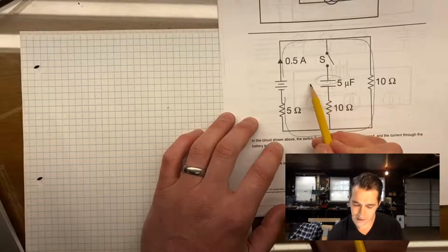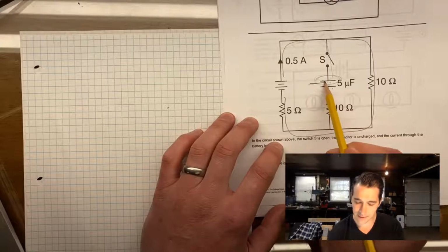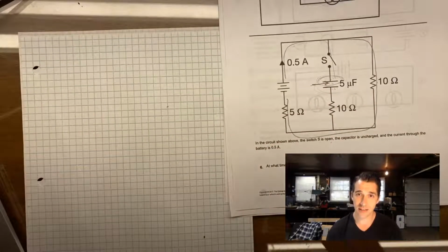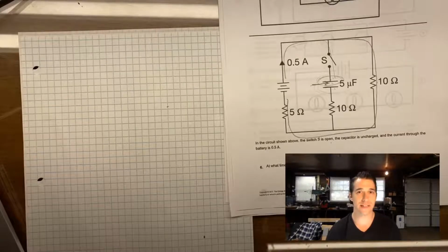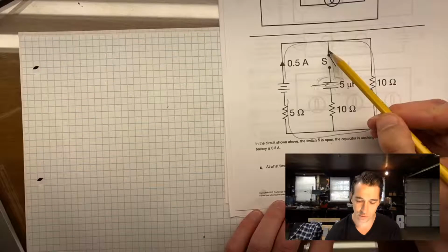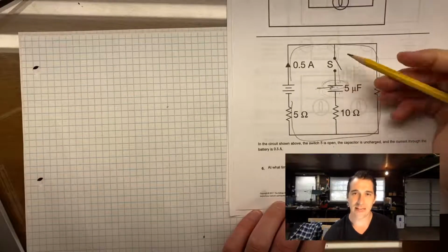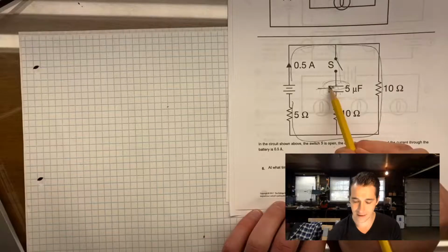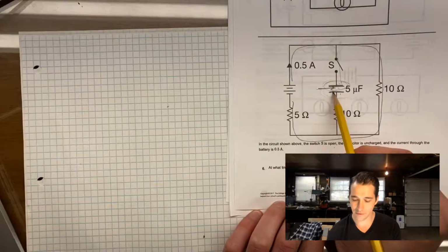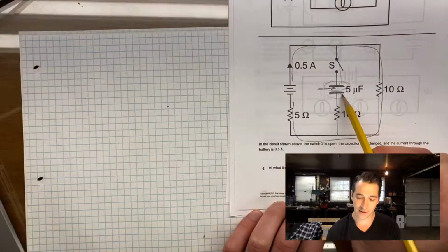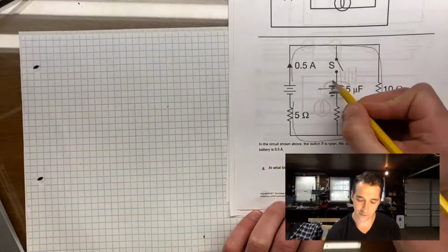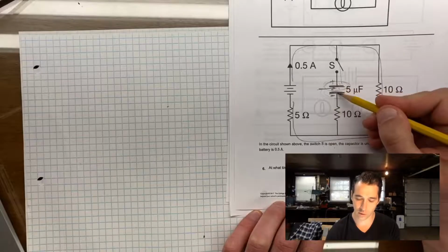I want to really make this clear. This gap inside the capacitor is actually a gap in the circuit. There's nothing connecting those two plates together. It's not going to continuously flow across here, okay? Even with the dielectric, that dielectric is stopping the flow. So what happens is this plate can interact with this plate and create an electric field here that will set up this charge separation, but current will never flow across this gap.